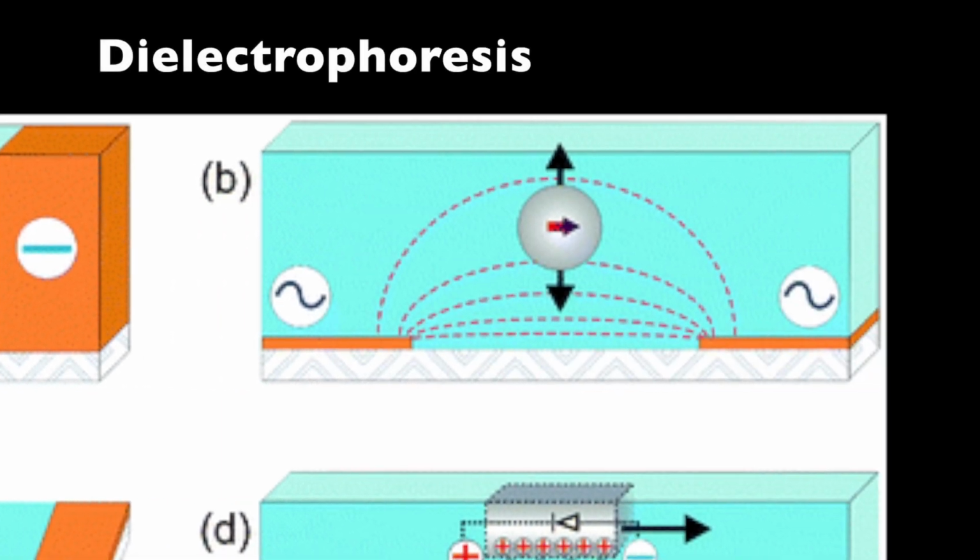Upon application of a DC electric field, particles migrate toward the electrode of opposite charge. Picture B shows the dielectrophoresis. So particles are attracted to or repelled from the highest electric field intensity region due to the interaction of an induced dipole with the gradient of a DC or AC electric field.